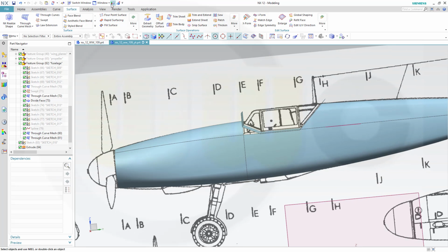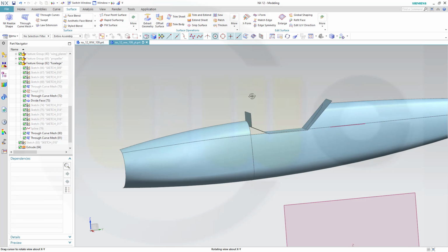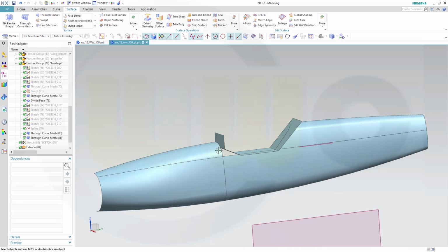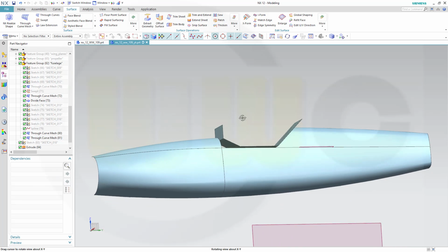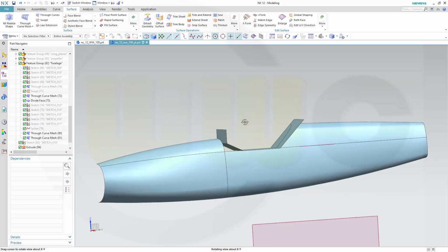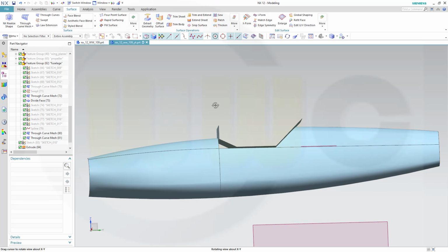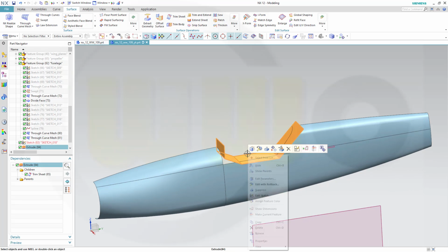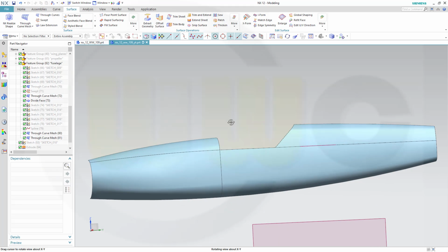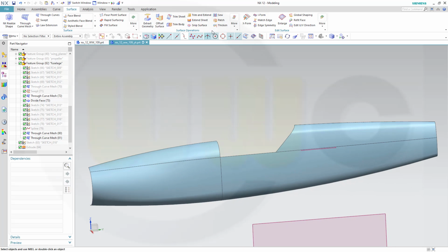Now maybe hide the image, close, and I need this to be extended in that direction. I could go for a sweep, or yes, a sweep along that edge with that profile. So let's hide the extrude and make a swept. Where's the swept? Surface swept.